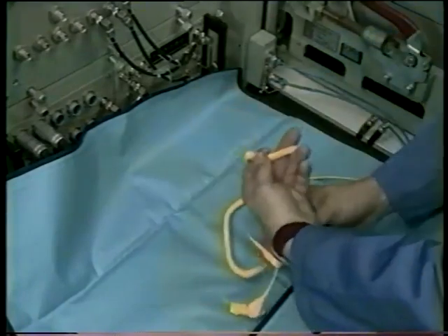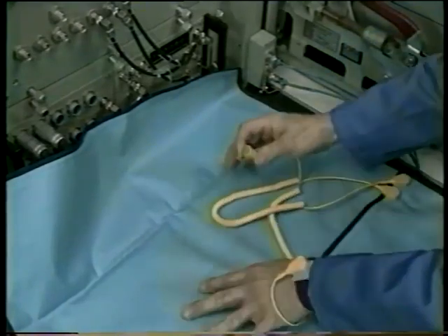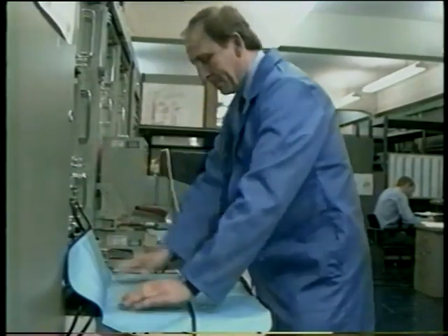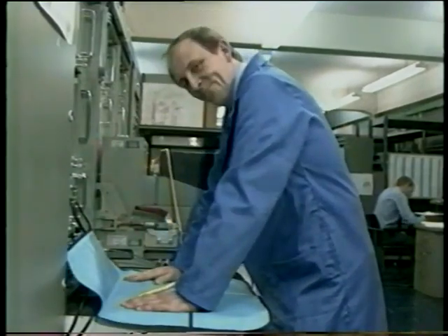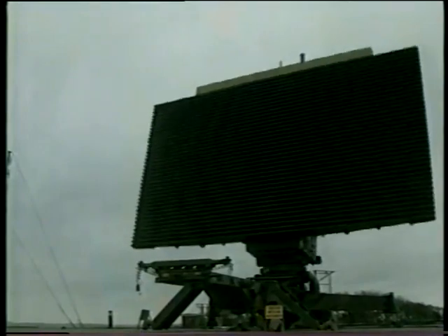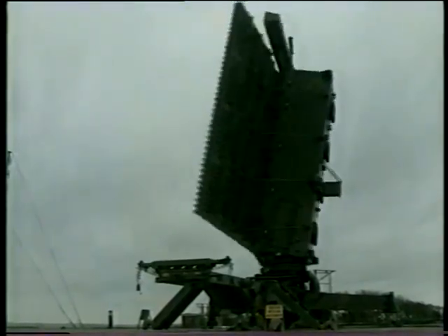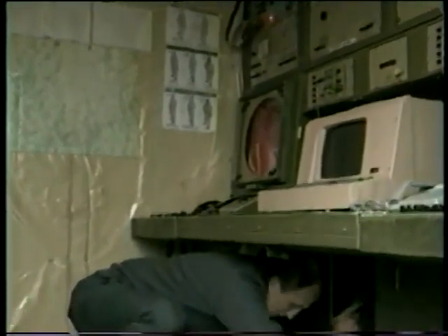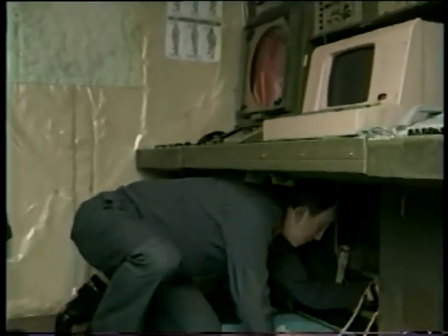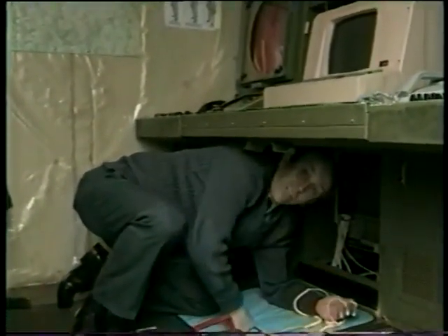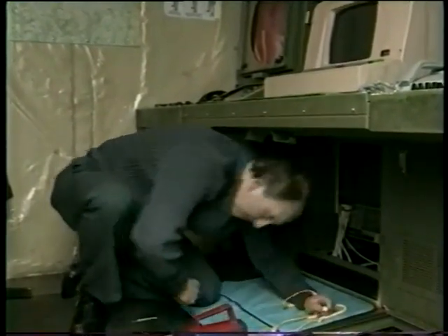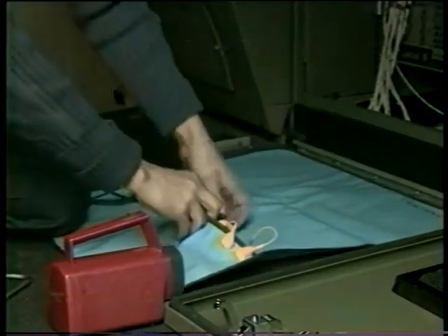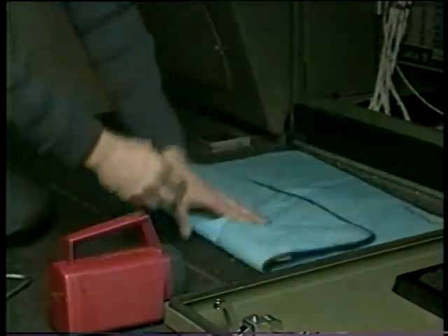You could actually use it here, where a quick circuit board change is needed at the test station, for instance. Just make sure it's grounded. But it comes into its own in those large installations such as flight simulators, ground radio, or radar situations, or Rapier. I don't suppose it makes any difference if I wear barrier creams. No, not as long as the strap is making good skin contact. And don't forget that the wrist strap and lead should also be tested regularly before use.